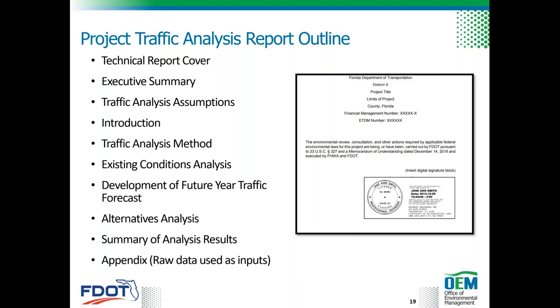And also it needs to include the alternative analysis section, which provides a description of the project alternatives, assigning of project traffic volumes to alternatives, and a summary of operational and safety analysis for each project alternative. Also, it needs to include a summary of analysis results.